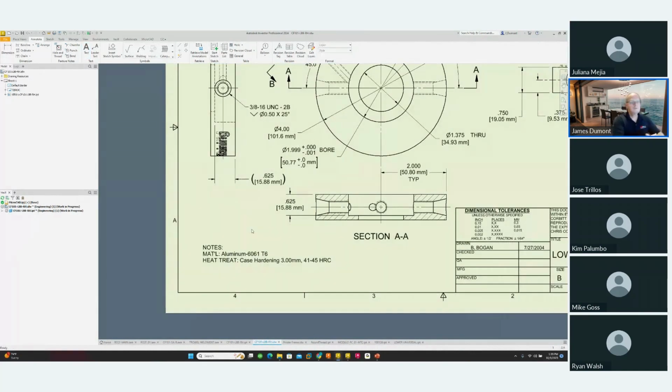So these are notes that'll be live and dynamic. Any change you make to the model, all of your annotations will update. And again, this is accessible through everything: bill of materials, iLogic, it all works. That's great, because we'll have drawings or parts that are old and we won't know what we did to them heat treat wise. Exactly. If we do it at the model level, the information's always there.